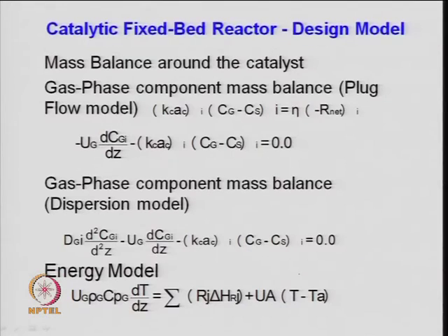So, a simple mass balance, as I discussed now, whether you write it for mass transfer or a chemical reaction, at steady state all these rates are equal. So, whatever you need, the input minus output minus disappearance because of chemical reaction in a reactor at steady state is 0. That is the very standard design equation, whether it is a fixed bed or multiple, your design equation will be based on the mass balance and the energy balance, right.